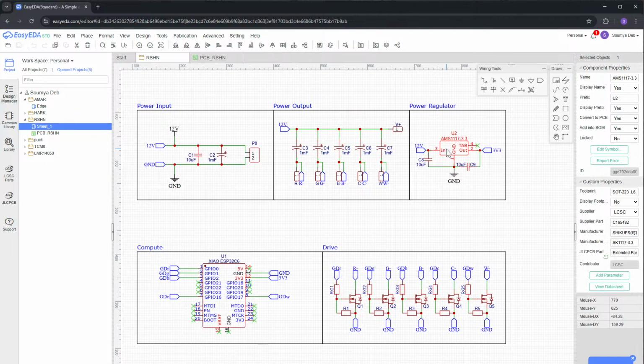And this is the AMS1117, which is a 3.3 volt regulated power input for the module, because we have a 12 volt input and we cannot power this module from 12 volt, so we needed the 3.3 volt to run this. And instead of going through a complicated buck conversion or anything, I just went with something simple and trustworthy. So a normal linear regulator, even though it's not efficient, but none of this is.